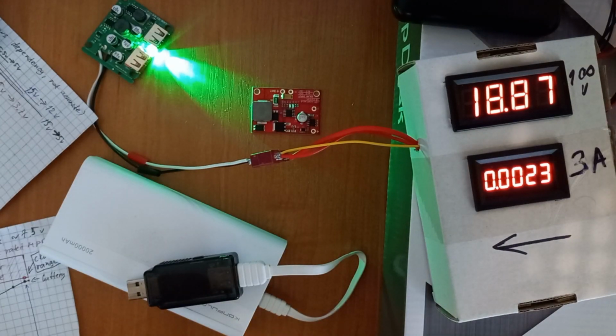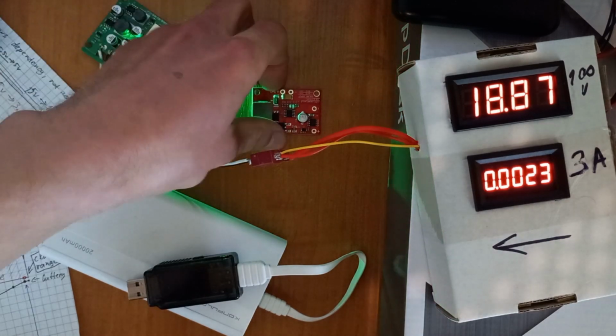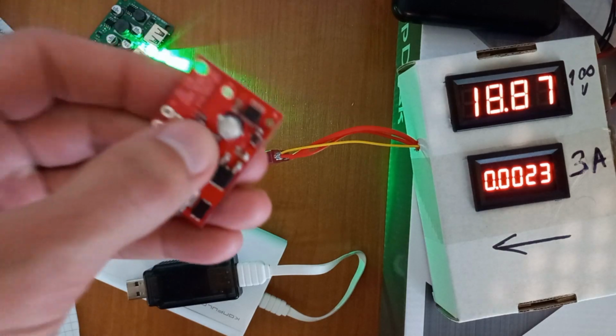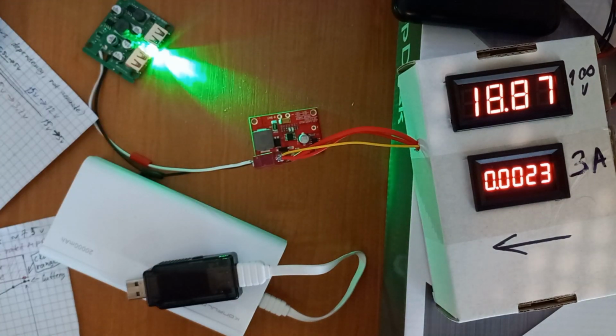I'll also refer to a video by Great Scott, link in the description, in which he assembled an MPPT based on a similar MPPT chip. I think it's actually the same chip. It resulted in poor efficiency, while he was only testing the conversion efficiency. There is also apparent fixed input voltage tracking according to the divider and the reference voltage that he mentioned, so the chip works badly too. Some sellers may mark simple DC-DC buck converters as MPPT and specify the chip it uses, while the datasheet of that chip doesn't even mention any MPPT.